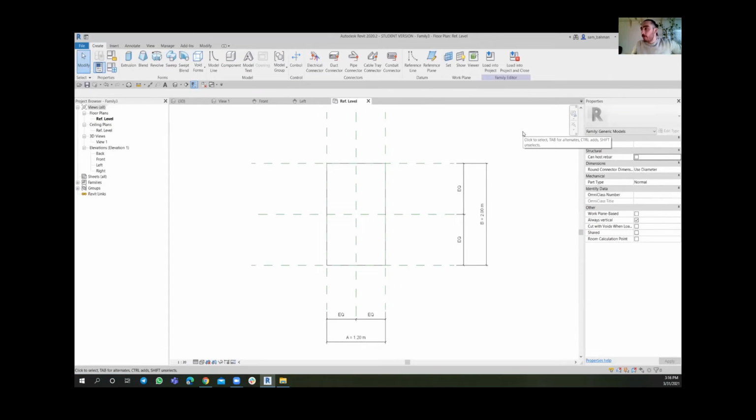So far we have reached the part where we are able to define the reference plane and then define the extrusion, and make sure that the extrusion is getting locked up with that reference plane. So once we define the parameters like that, we would be able to change the distances between the reference planes. The extrusion that is already locked to that reference plane has to follow the reference plane that we have. So I would say the reference plane is kind of dominant. Whatever change happens to the reference plane, without any other choice, the table or the extrusion part should be following.